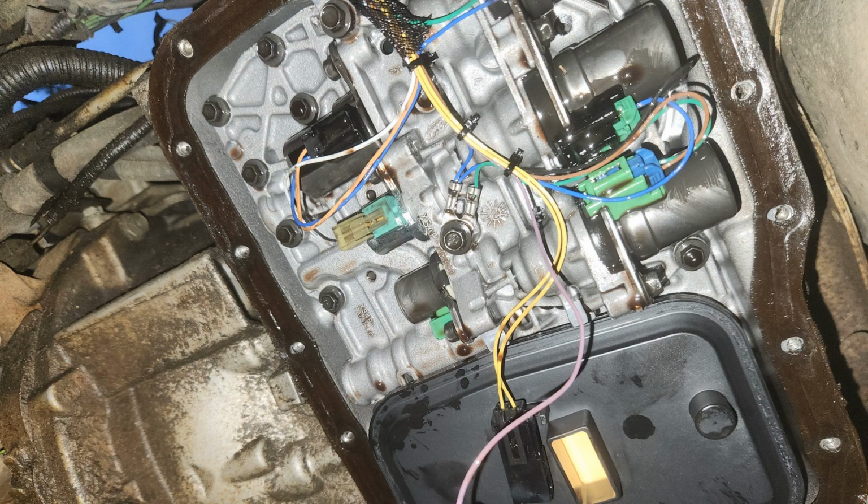To do this, you will need to check the manual for your car, find the solenoid block on the automatic transmission, remove it, and remove the faulty component. Further, being extremely careful and attentive, the solenoid is disconnected from the power supply on the detached automatic transmission hydroblock and removed. In its place, a similar element is installed, corresponding to the type of transmission. It is obligatory to use a new gasket under the solenoid. Usually the gasket is included with the part.